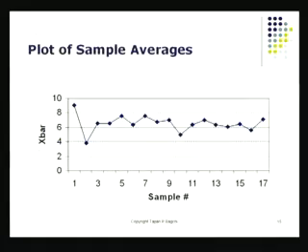And that's the one that I plot. Those are the ones that I plot on a chart. And I try to see if the plotted X bar value or the R value is within what we call control limits. If we do that, we'd be preventing a lot of quality problems.